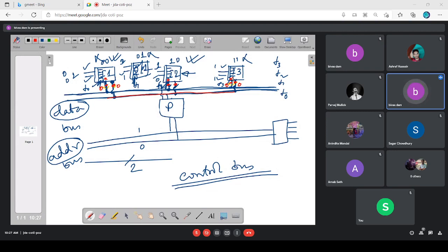But if my internal input devices, the internal circuits, are all developed with the help of TTL logic families, in that case, we know that two totem-pole TTL outputs can never be shorted together. But here there is a basic requirement of output shorting.